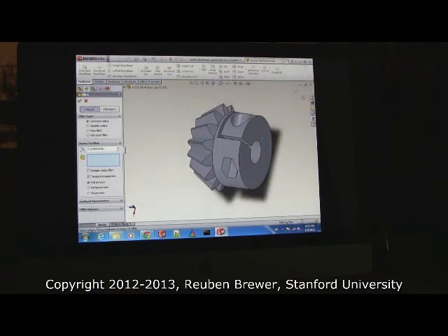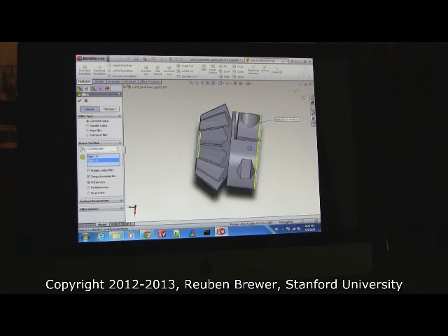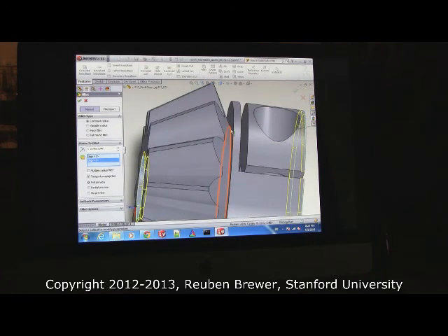And everybody look at my screen. Select this edge here. If that doesn't turn yellow, press full preview. Okay, does everyone have that fillet? Alright, rotate your part and get this edge right here. This one's important. Rotate your part and get this one. Now, let me remind you, we're 3D printing these gears. Does anyone know why I'm taking this edge right here?